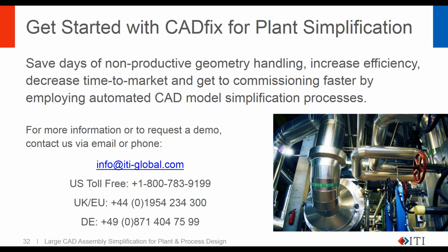So for the JT, to be clear, they asked, does it need to include the solid geometry XT or JT BREP, or can it be simply surfaces, tessellation, triangles? I guess sometimes you can import and export requirements, could be that it's solid geometry only. Yeah, most of what I've been talking about today has been with processing solid geometry, so BREP geometry. We can import a JT file that contains the BREP and the tessellated representation.